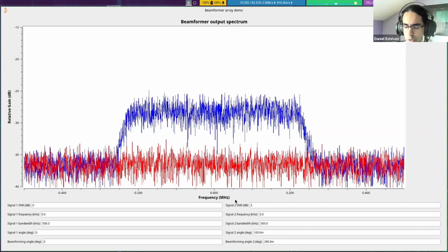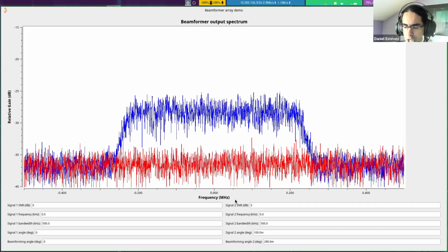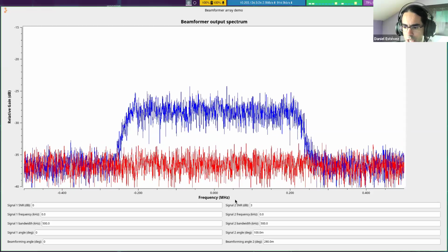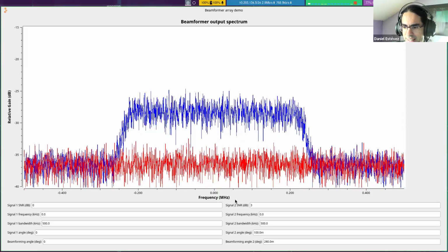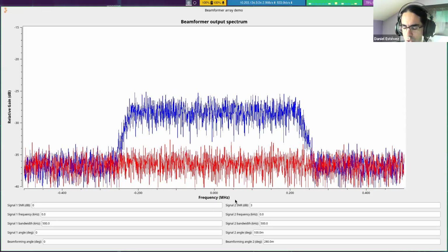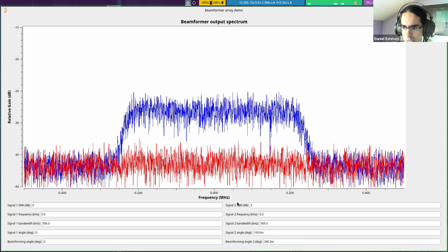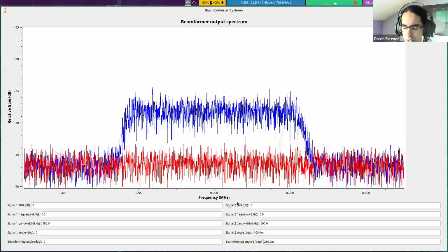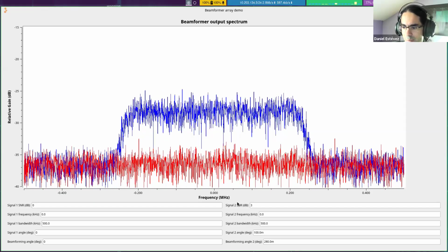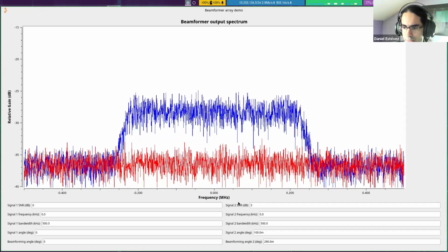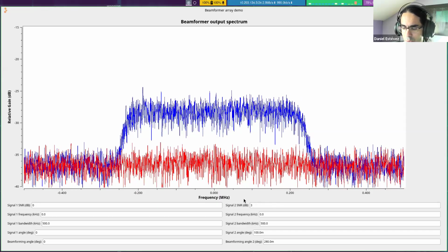Yeah, also something useful about beamforming is that even if you are not using multiple beams, it changes instantaneously because it's only changing some numbers in the computer. Whereas dishes, if they are large, they take a while to move. So that's also useful in some applications where you need to track an object really fast or something like that. The term is electronically steered array, and you can imagine why it's called like that. And it steers very fast because it's all just numbers on a computer.